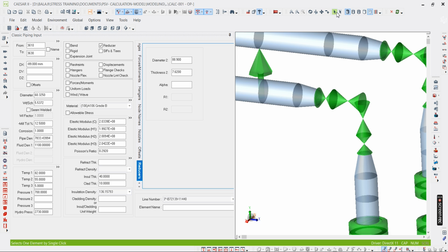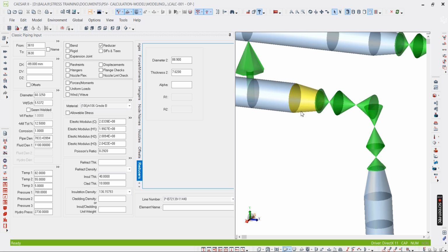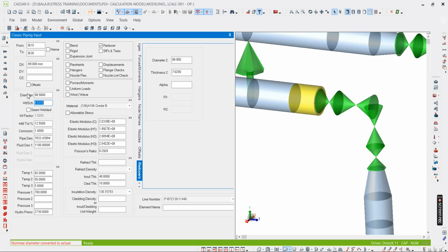For this, what we applied yesterday, from small bore to big bore, we defined that there is no need to change at this node number. After this node number only, you need to change the diameter. That person, what he did, he just entered here, and here he has given 2 inch. So it is in the reverse way. It is not the correct way.